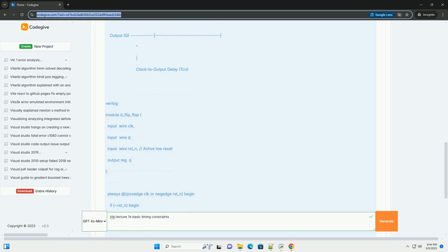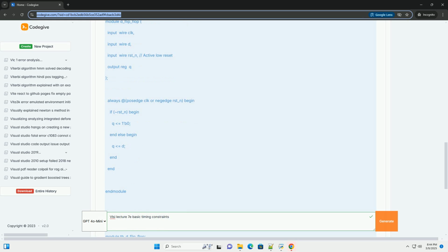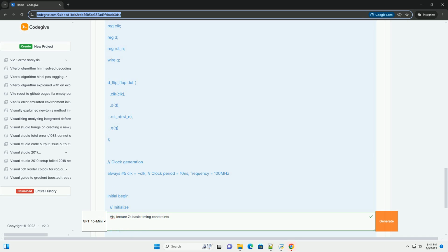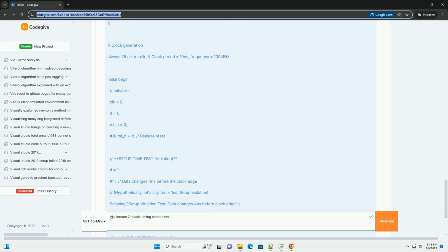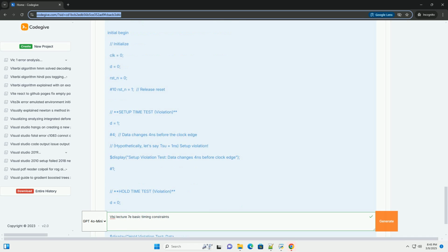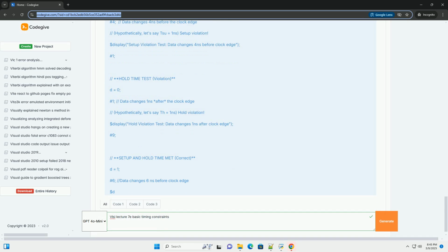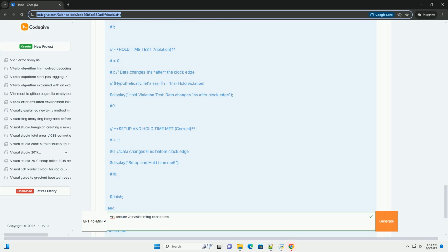In synchronous digital circuits, timing constraints are critical for reliable operation. They dictate how the timing of the clock signal and data signals relate to ensure the sequential elements, primarily flip-flops/registers, capture the correct data. Violating these constraints leads to metastability, unpredictable behavior, and potentially system failure. The two primary timing constraints we'll discuss are setup time and hold time.